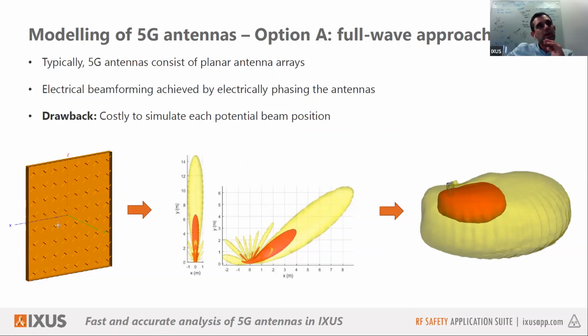It's not a detailed model, but it's a representation of what an antenna array might consist of inside one of these 5G systems. It's got a number of elements. These are cross dipoles, and those antenna elements, positioned in front of a reflecting surface, can generate for us this very narrow traffic beam. And we can match its properties from information that we get from the manufacturer.